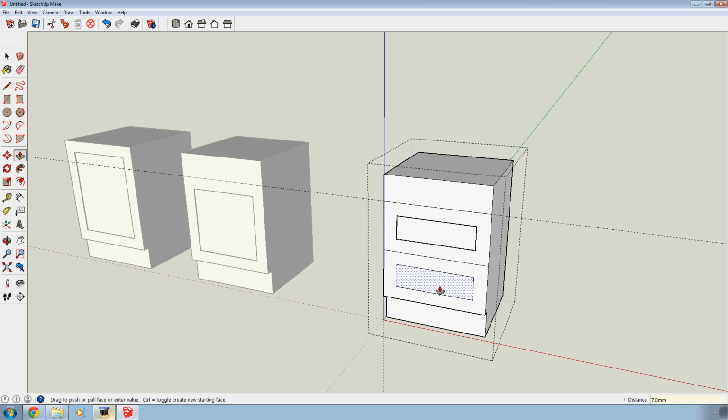Now I'm going to show you another feature of SketchUp. I might be using this tool a lot, and if I tell SketchUp what I want it to do, then it'll do it. One of the ways of doing it is to show it something that it's just done. So if I go like this and then I move up onto here, now if you look at the box down in the bottom right hand corner, it says -7, which is what this face is.